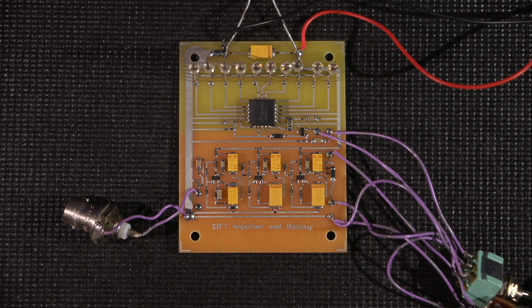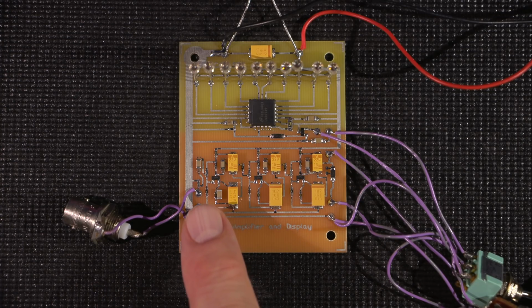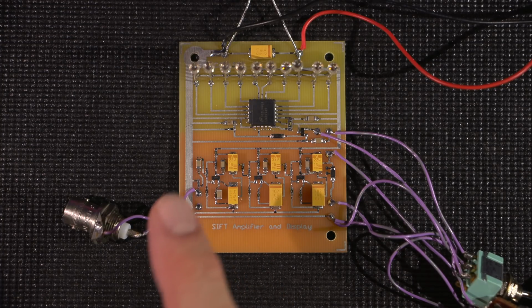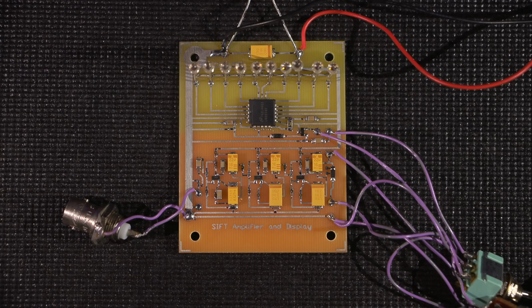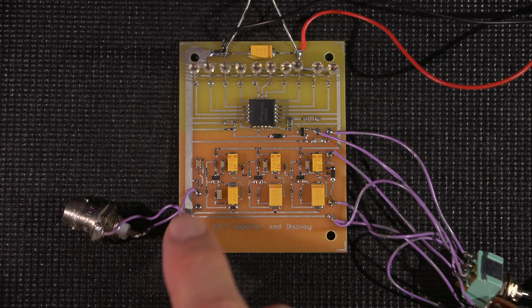In order to start off this troubleshooting procedure, the first thing that we want to do is take all the knowledge that we know about circuits like this, things that we're familiar with from working on other things, and put that to use here. So first of all, some of the things that we already know about this circuit is that we have an input here, and that would be pretty obvious if this was an audio amplifier because it would be running up to some form of an audio jack, whether it's an RCA or BNC or XLR or something like that, right? Now, the rest of this would be simply following the traces.